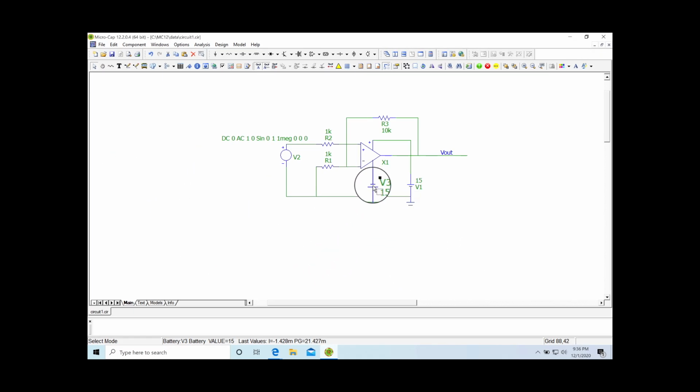And I'll drag it down here, and now it's connected. Everything's connected to my return. Now guys, I could have put a ground symbol on each one of these things, but people have kind of got carried away with doing that. It used to be we connected everything together like this, so it was obvious to the eye where everything is connected, and used one ground symbol. But people put ground symbols everywhere because they're just being lazy.